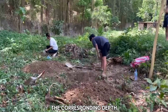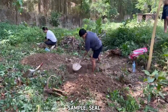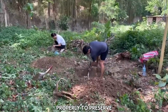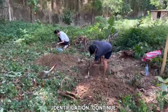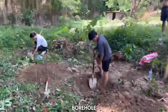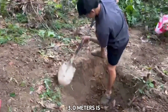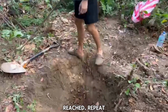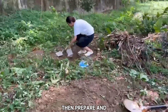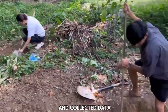Record the corresponding depth and all relevant observations for each retrieved soil sample. Seal each retrieved soil sample in a container and label it properly to preserve its condition and identification. Continue extracting soil samples during the succeeding borehole advancements until a depth of approximately 2.0 to 3.0 meters is reached. Repeat procedures 1 to 4 for borehole numbers 2 and 3. Then prepare and draw the site stratigraphy based on the observed soil layers and collected data.